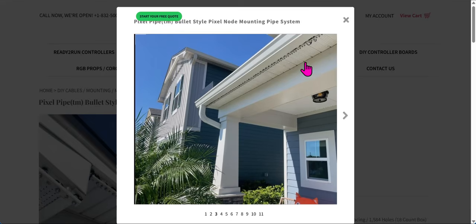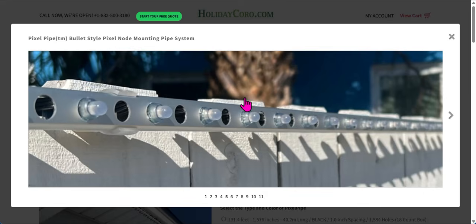You are going to get some cast glow off of this, so you're going to have a little bit of wall wash because this product is facing downward. And if the customer had wanted it facing outward, they would have needed to either space this off, and we'll talk about some of the spacers, bring it down, and then tweak it to make it face outward so it would not have a glow on the house. So you can design this exactly the way you want.